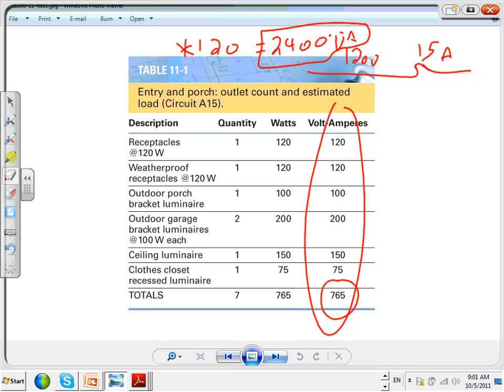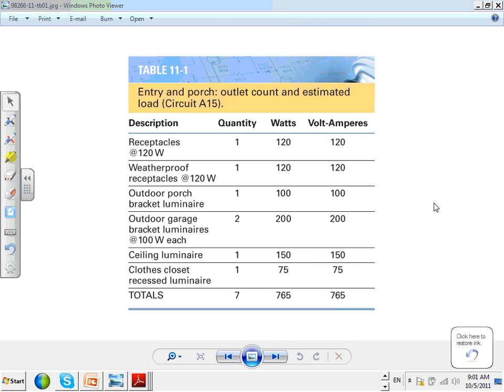And if you use a 15 amp circuit, what did they put, 20? And that will get you what? 1800. Exactly half of that, almost. 1800 volt-amps. Am I okay? Have I exceeded the limitation of this circuit? No. So that's why these are cool stuff.